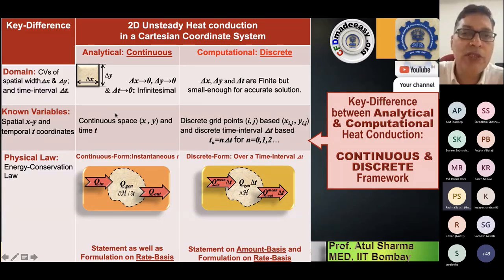In both cases, whether you consider analytical fluid dynamics or computational fluid dynamics, we start with the physical law, such as for heat conduction, the energy conservation law. And when we apply it to a control volume, there are two forms of the energy conservation law which we have studied. One which we studied in a thermodynamics course, another which we study in a heat transfer course. In a thermodynamics course, the heat is presented on an amount basis. In thermodynamics, we talk of the amount of heat, whereas in a heat transfer course, we talk about the rate of heat transfer.